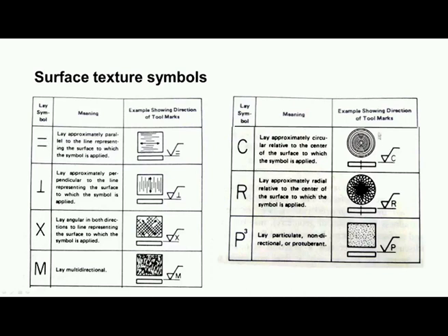And then if the surface texture is concentric like this, then we use this particular symbol. This happens when we turn the workpiece in the face turning operation.